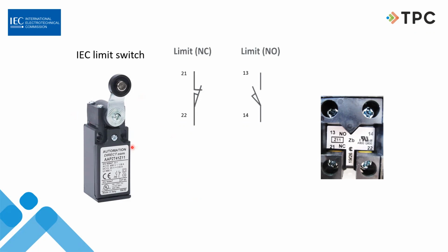Now, if you work with a lot of hardwired stuff, one thing I would tell you is that in some of the better, more expensive limit switches, up here in the operator section, there are actually cams, and you can make the switch so that it only works in one direction. So if I push it this way, it works, but if I push it this way, it doesn't. I can set it up for vice versa, or I can make it work in either direction, so it passes current either way it goes. So if you have problems, or you're checking or replacing switches, make sure it doesn't have that up there, because it may only want to operate in one direction, and the other direction could cause you problems.